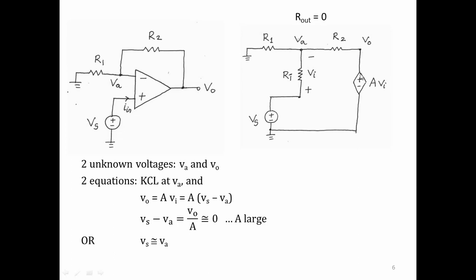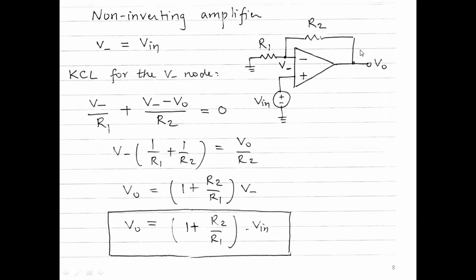We've seen this earlier. We do not know currents in dependent sources as a function of the voltage across it. The current in voltage sources is determined by the rest of the circuit. So one never ever writes a KCL at the output node in an op-amp circuit.